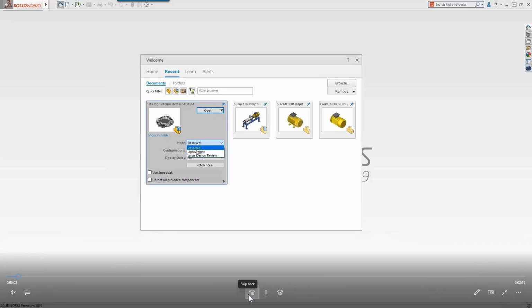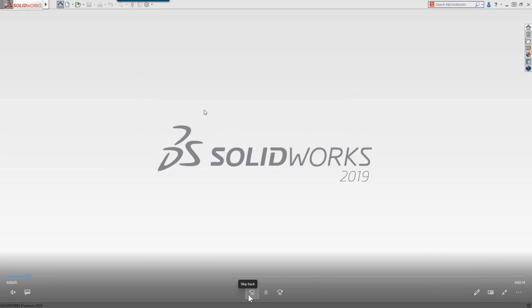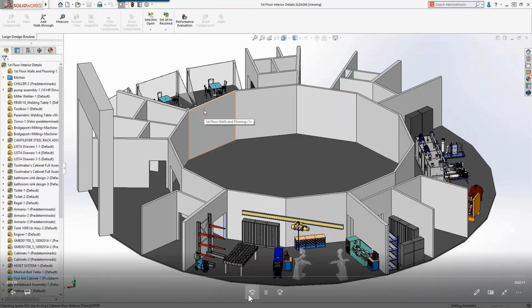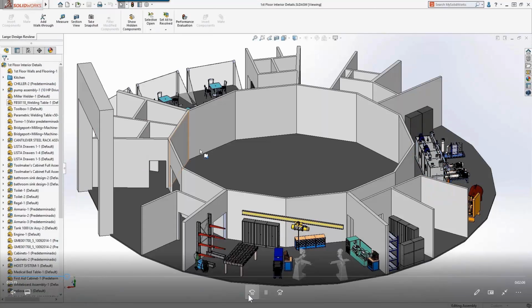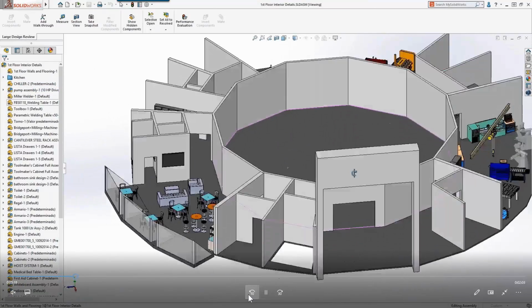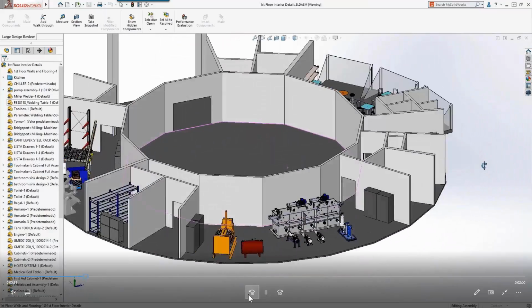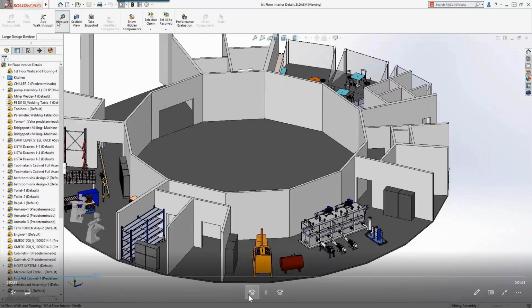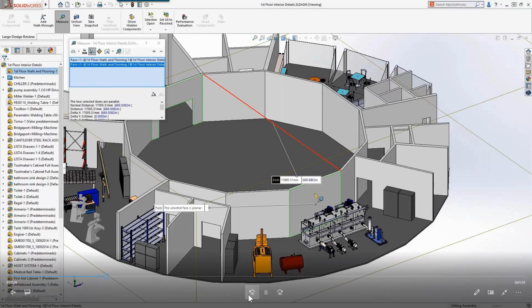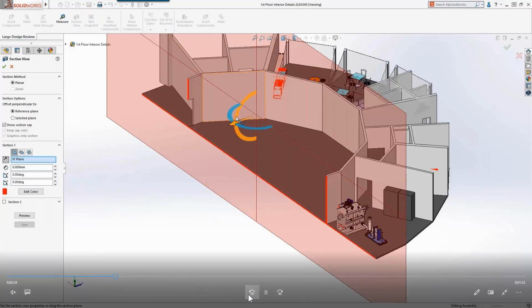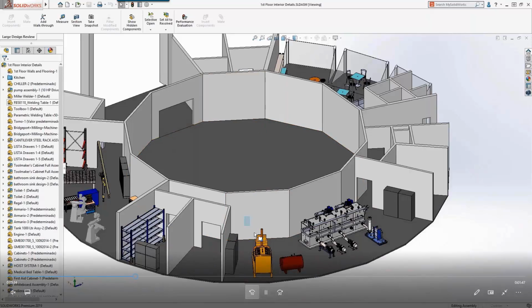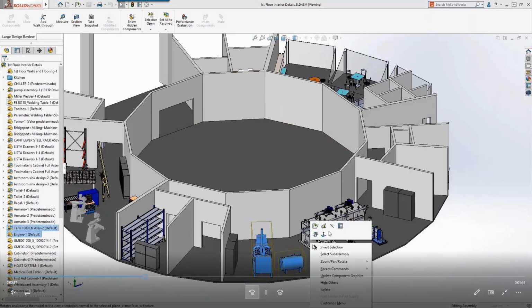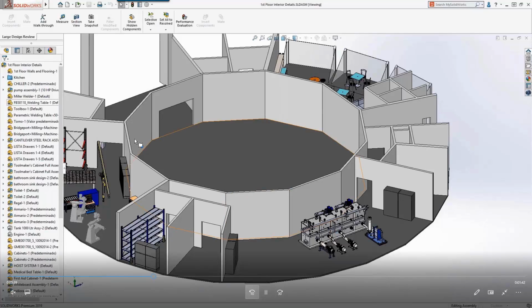Large Design Review is a capability that has been available in SOLIDWORKS for many years and allows users to open very large assemblies lightning fast, giving them the ability to quickly interrogate a model or conduct design reviews. In Large Design Review, users have access to the FeatureManager, and it provides super fast view manipulation to rapidly visualize and move around your assembly. The ability to measure distances, cut across sections, hide and show components, and do walkthroughs are also valuable tools to interrogate a large assembly. In 2019, Large Design Review has been enhanced to include assembly editing capabilities.